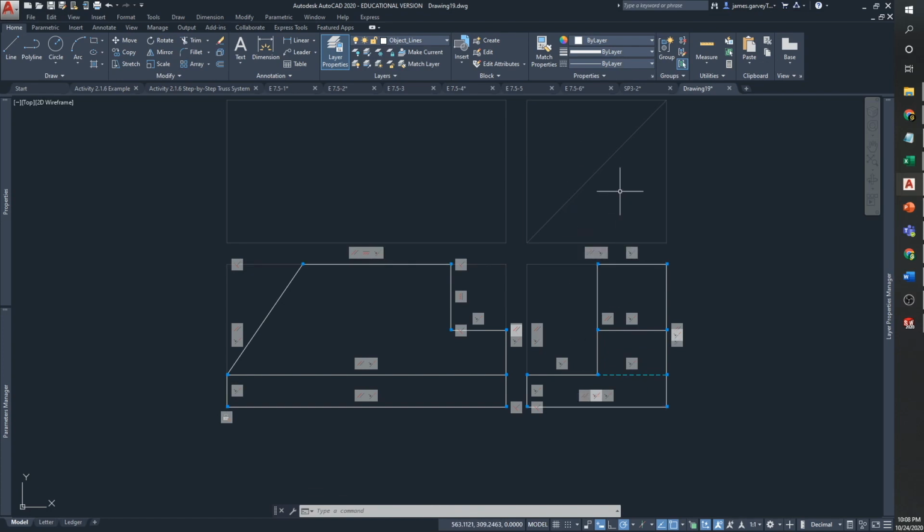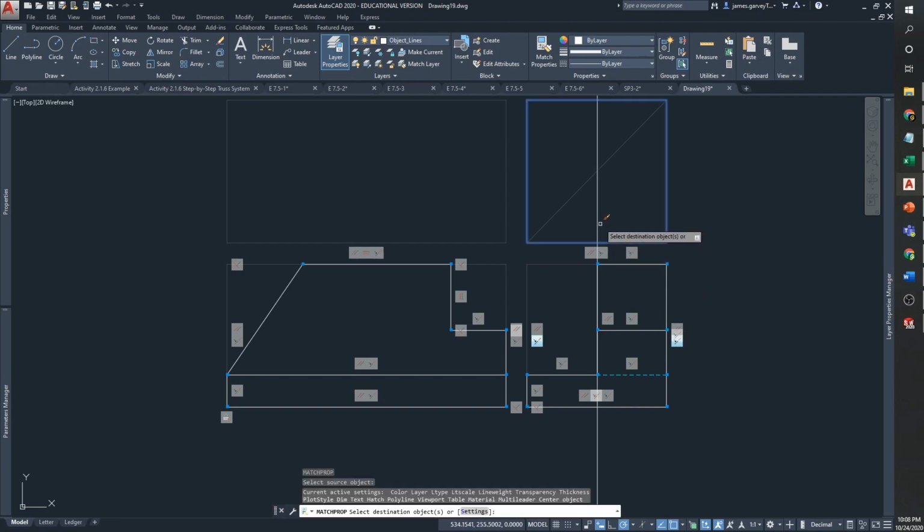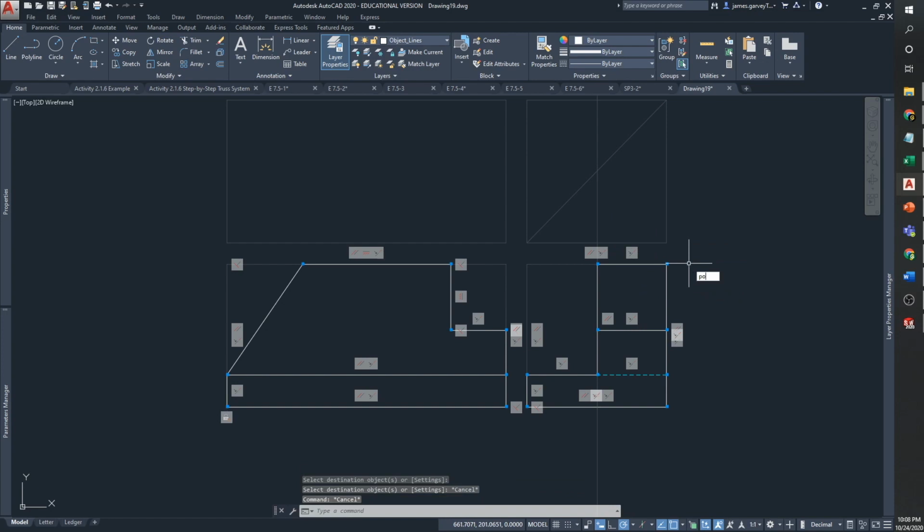Okay, so now to get my right view and top view connected, I'm going to use construction lines and points. Those construction lines and points will go on my miter line. I'll get those constrained. So as those adjust, they'll slide along this line and make sure that these two views match up. So set XL. I'll do match properties real quick to make that construction. PO for point.